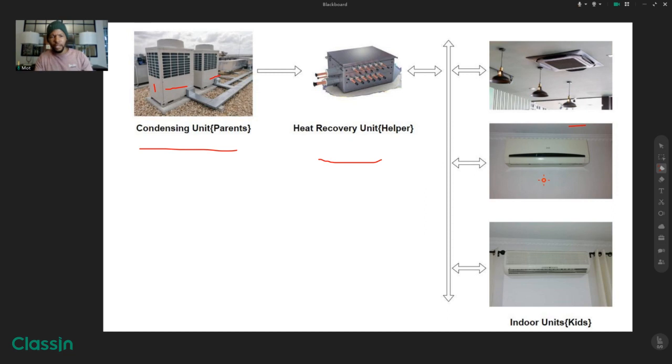Then you have your piping and you have your ref nets. Ref nets just help you to have an even or balanced flow of refrigerant to the BS box, or where you're going to separate or have different BS boxes, and there are multiple requirements on the distance from the ref net to where you're going to make your joint or before, depending on different manufacturers. So these arrows would indicate the communication. Basically, that's how I analyze this kind of system.